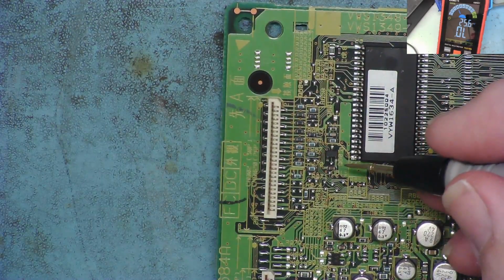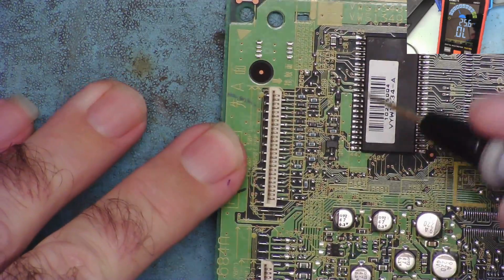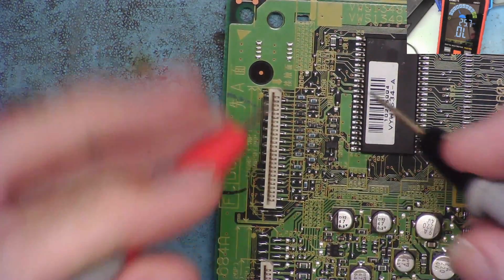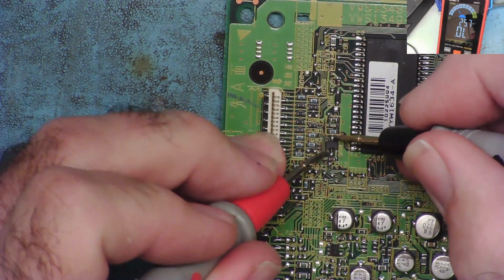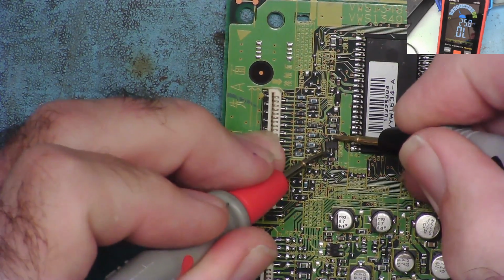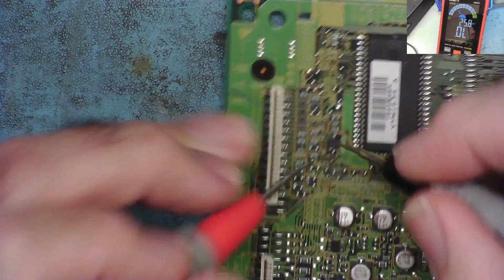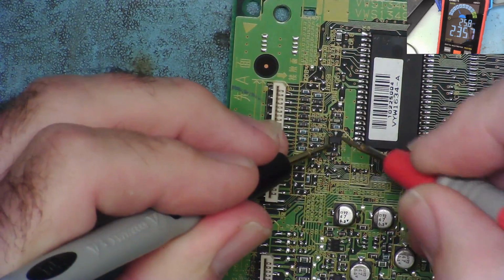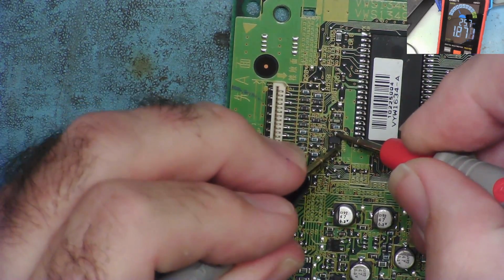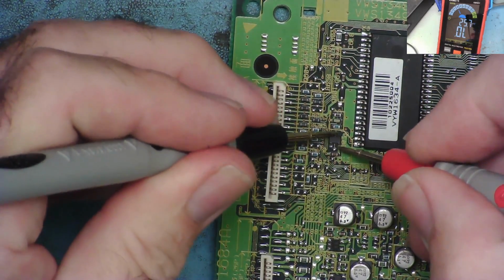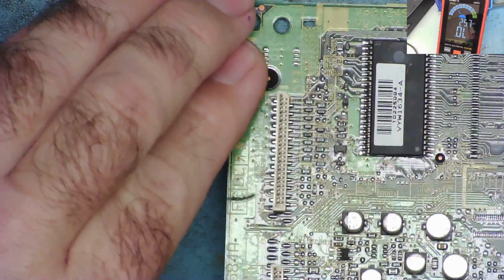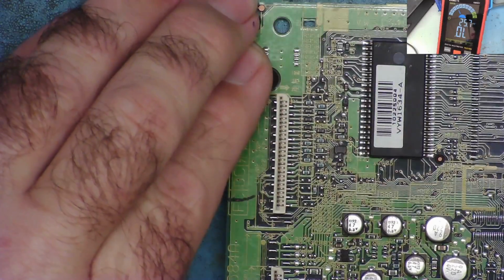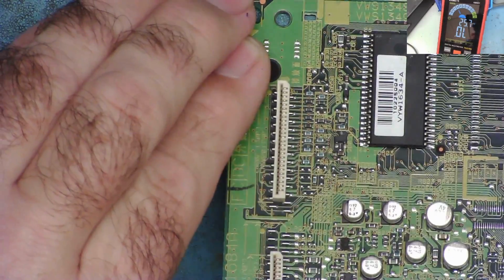There's another one here. Let's see, is this a transistor? We don't know. Again, this is on a thick track, so it's probably the emitter. This is probably the base, but it could be a MOSFET again. So let's have a look what we've got. Nothing there, nothing there. Go the other way around. Yeah, a reading, but it's not a semiconductor junction. Okay, so again, we can't read anything from that, and we'd have to look up the code again. SMD code, yeah, SOT-23, and now we'll see if we can find out what that is.